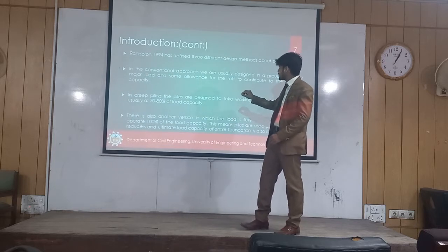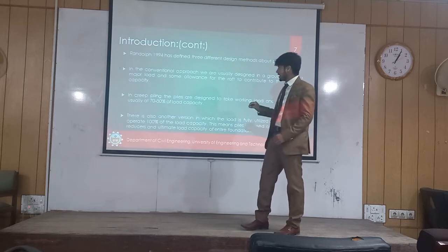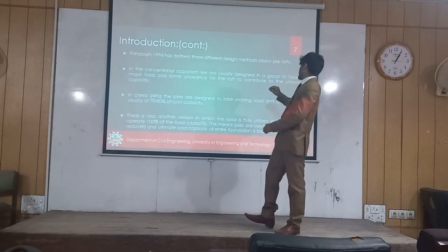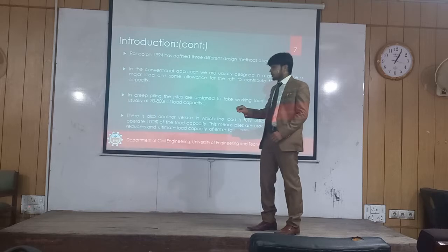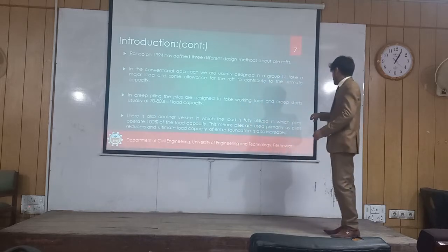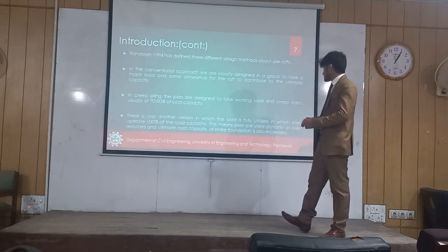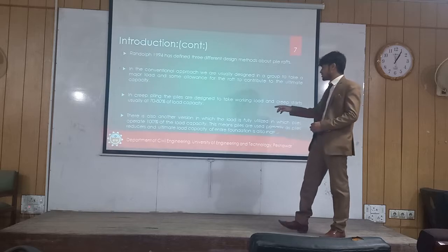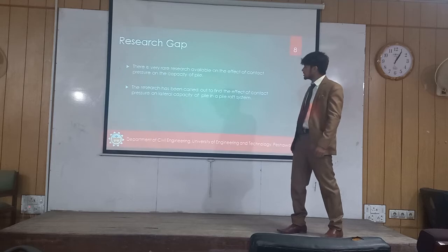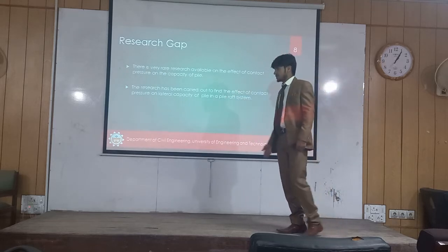In the conventional approach, piles are usually designed in a group to take the major load, with some allowance for the raft to compute the ultimate capacity. There is also another version in which the raft is fully utilized, in which piles carry 12% of the load capacity. This means piles are used primarily as settlement reducers and the ultimate load capacity of the entire foundation is also increased. For the research part, I would like Mr. Rahim to come here and explain it.